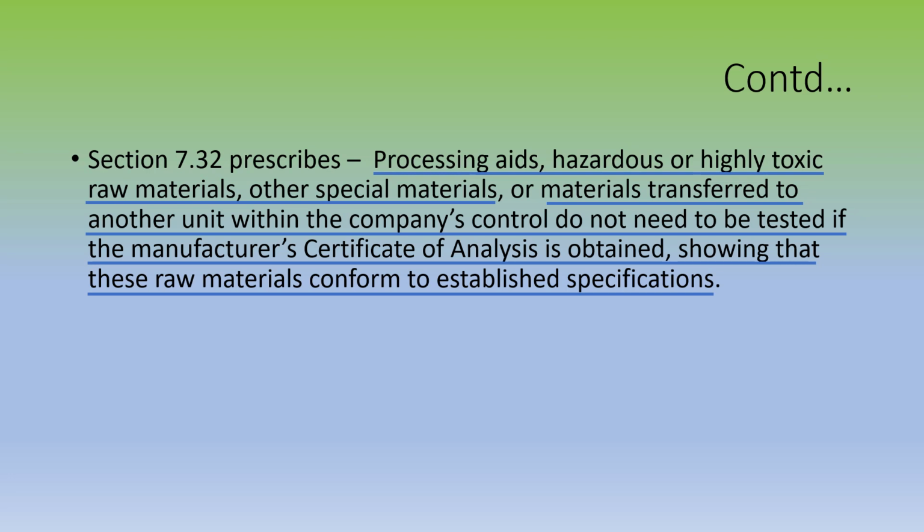Processing aids like filter papers, filter pads, high flow supercell, and fuller's earth that are used as filtering media have specific testing requirements. All API or intermediate manufacturers may not be equipped with such equipment for testing on site. In such cases, the certificate of analysis may be accepted.